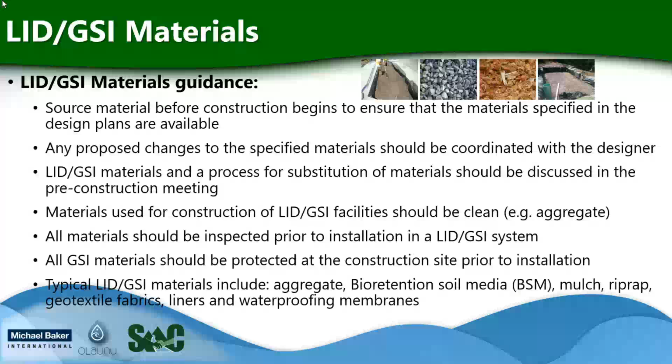All GSI materials should be protected at the construction site prior to installation. Protection includes covering and perimeter control around stockpiles of LID and GSI construction materials. LID and GSI materials should not be delivered to the site until just before their construction. This will reduce the incidence of contamination of the system materials. And then also avoid placing LID and construction materials in concentrated flow paths and or near catch basins.